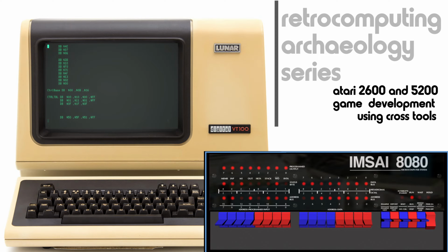Almost there. This is controller tables that translate controller movements to velocity values, sound tables to translate sound tones to their register values, player widths, a color palette table, and finally, down here at the bottom, we see PF0_0, which are the values that go into the PF0 register for this particular stage right here. So first stage, PF0 values.